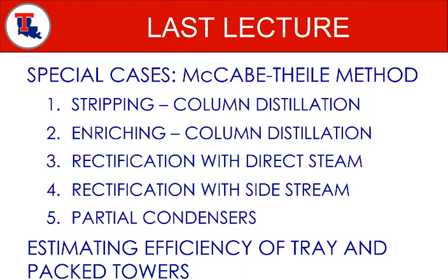It tells you how close to the equilibrium you can go in the vapor phase. That is very important for us to know, because that's when we start transferring all of our knowledge to build McCabe-Thiele diagrams, to go from a theoretical point to a real point, doing a real tower design.